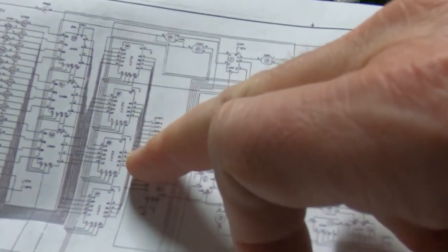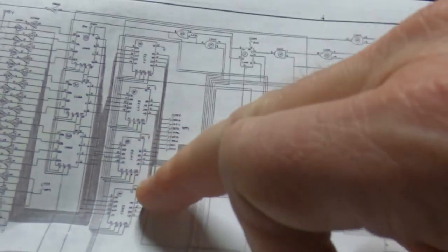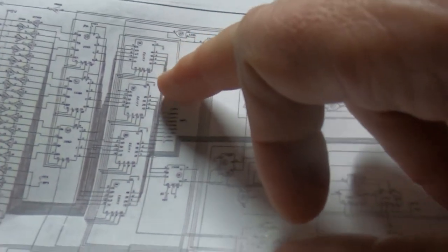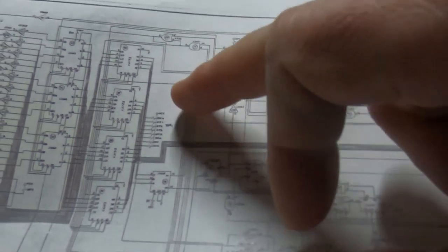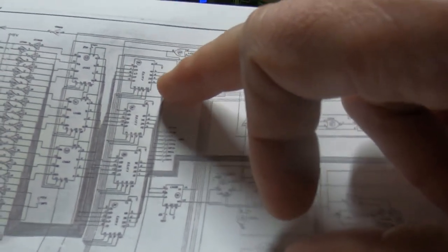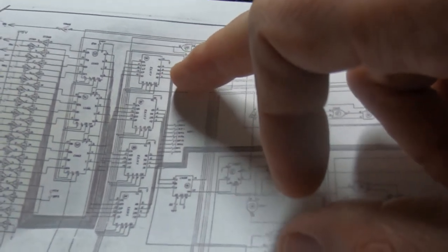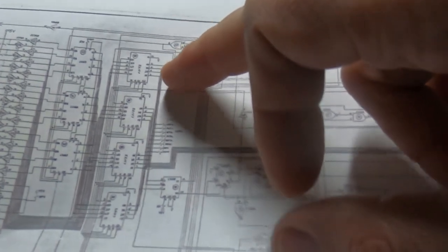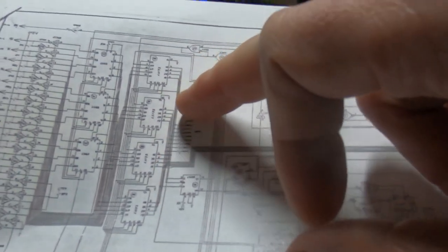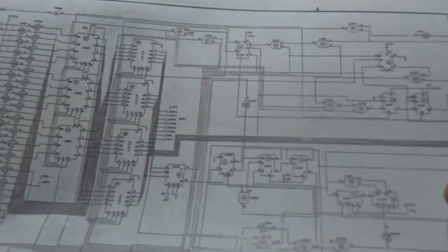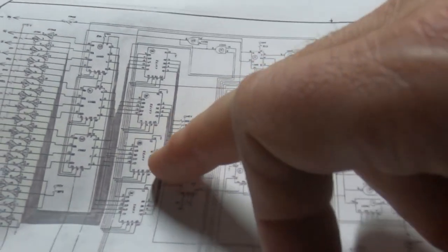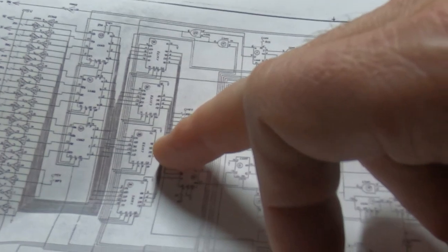And also, because these are in pairs and they've got tri-state outputs, but they are predominantly working, and the correct characters seem to be, or at least to a certain extent, seem to be appearing on the screen, we can be fairly confident there are no dead shorts on the outputs of these, otherwise it wouldn't work to that extent. So I think one of the outputs is open circuit on this.